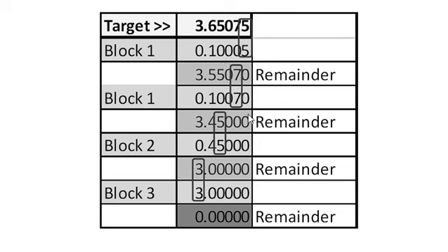And here we can see the whole thing. We started out, this is the desired height, your first block. The end has to be the same. Subtract it, you get your remainder. Go and get the block with the same end, right? Same end means this digit, the last digit, is a 0, and the last digit of your selected gauge block is also 0, and then subtract. Check the end, choose the same end gauge block, and then subtract it.